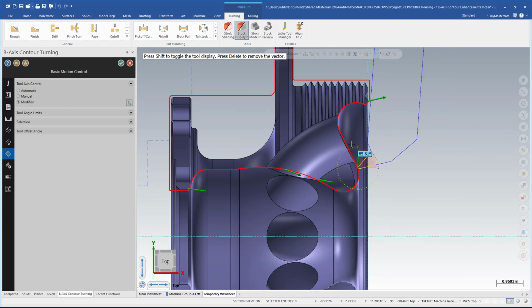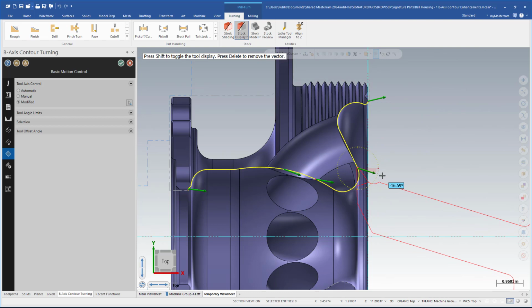So it's noticing a collision here. At this vector, when we try to do this rotation, we have a collision, so it won't let us do it. Same if we go this way. Notice that it turns red here. So this is not hitting a collision necessarily, although I think in this case it was, but it will also turn red if you are beyond the limits of the rotation of the machine. So if you're trying to push it too far, it won't let you do it. So let's see, I think I said 55 degrees. We'll do it like that.